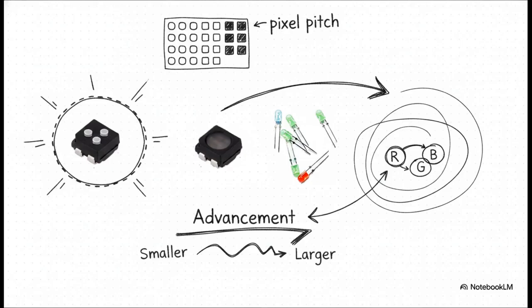But the SMD, or surface-mounted device, encapsulates all 3 of those color chips into one incredibly tiny flat package. This microscale packaging difference dictates everything from the pixel pitch to the viewing angle, which can actually reach up to 120 degrees horizontally. It even affects the color depth, pushing modern displays from 8-bit systems with 16 million colors to mind-blowing 16-bit systems capable of rendering 281 trillion colors.